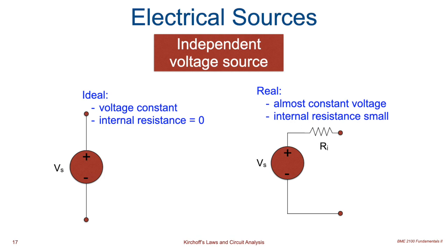And so we change the schematic diagram. We say, well, let's pretend that a real source is like a perfect source connected to a resistance, which we hope is small. That's the internal resistance for that source. And then we just put that little circuit in to replace our perfect battery, our perfect voltage supply, and we got something we can actually use and have a little more confidence that it's realistic. So there's times when we use the ideal source, there's times when we won't. It really, as with all these things, depends on how much complexity we need to answer a particular question.